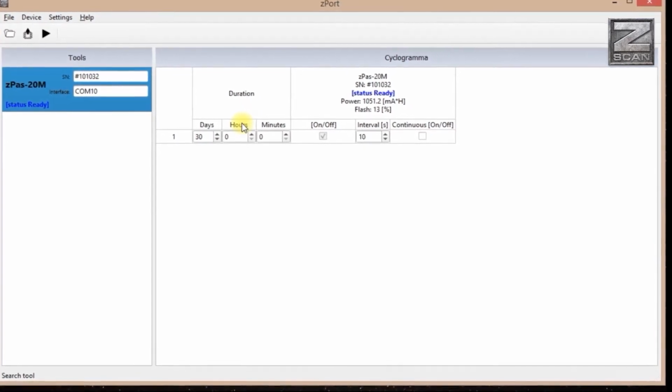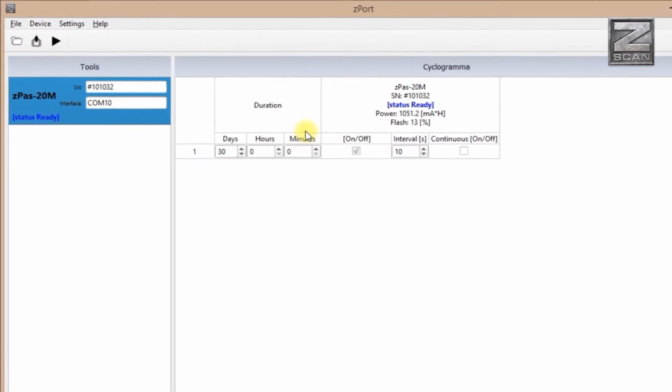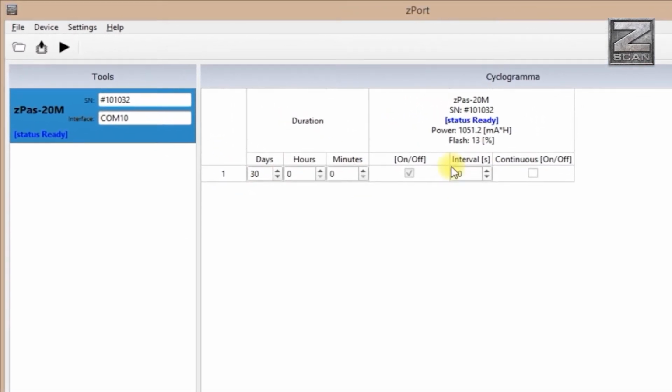Indicate the program according to the geophysical survey plan. Specify the time intervals and frequency of recording. In order to add an additional line, you need to right-click. After adding an interval, you need to set the necessary parameters for it. The program can contain 16 entries in total.